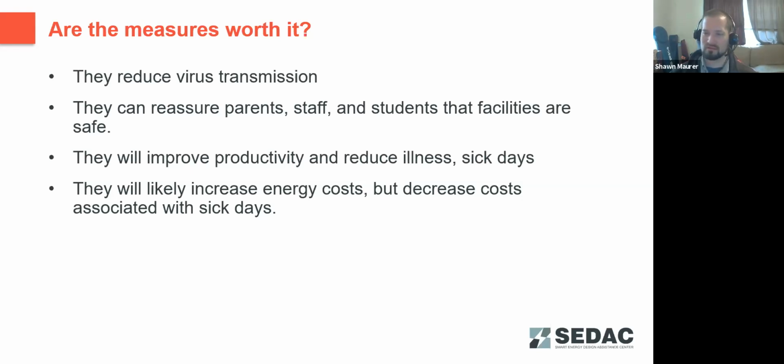So you might want to put it, just as an example, if airflow goes from over a teacher at the front of the room, passes over students moving towards the back of the room, and exhausts out the back of the room. Ideally, in that situation, you would want your air purifiers in the middle of the student section of that room, so that dirty air is drawn in from the front section of the class, cleaned, purified, and then passes over the back section of the class. That maximizes the amount of clean air those people are going to see.